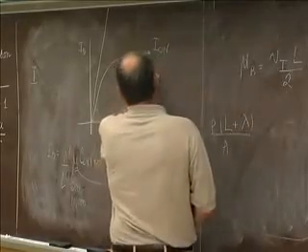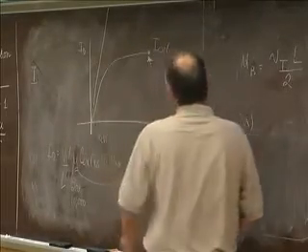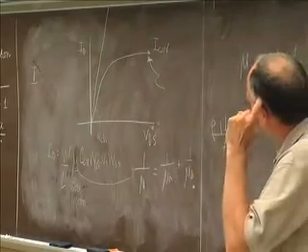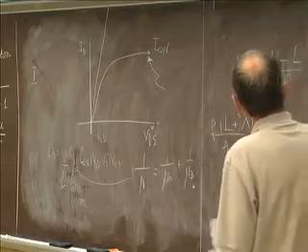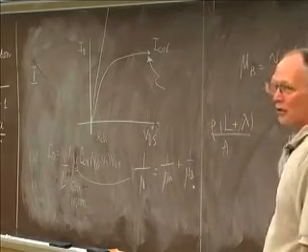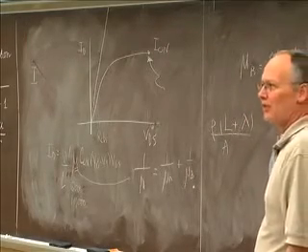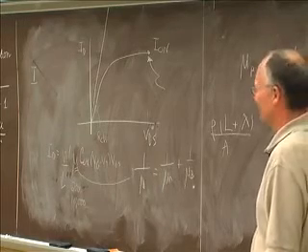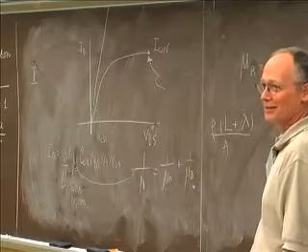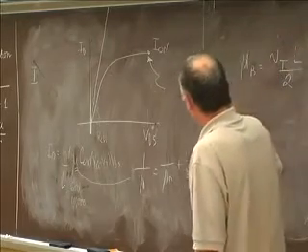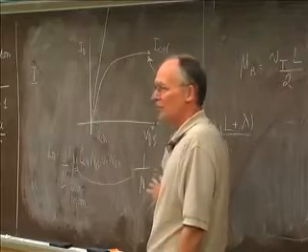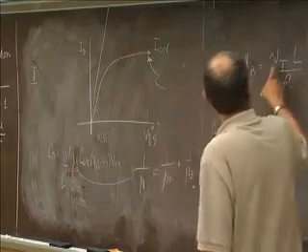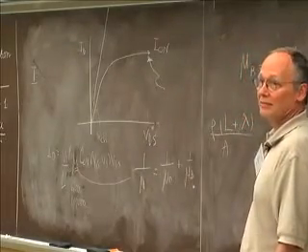Now, also up here, you tend to get more current. You can see that this mobility has a thermal velocity. So in 3-5 devices, it's a little bit harder to think about it in graphene, but you have to think about what the effective mass is in graphene. But similar things happen. If I have a high mobility because I have a very light effective mass, that light effective mass is also going to give me a very high thermal velocity.